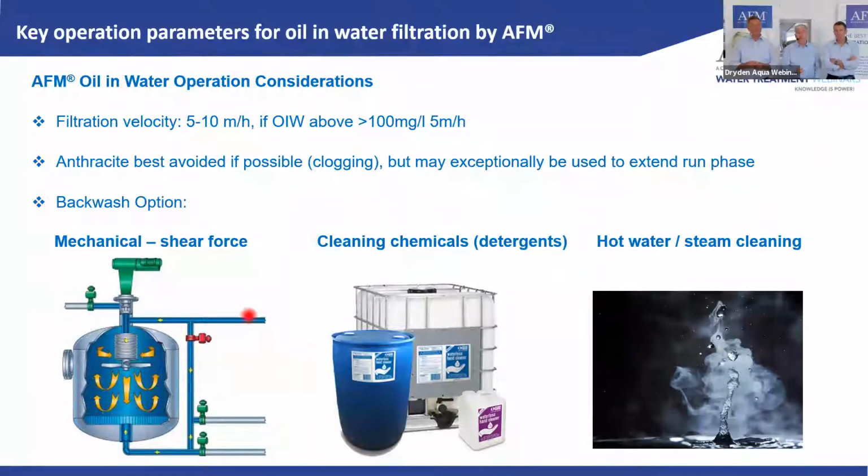So backwash options with the oil treatment, you typically have 3 options. Mechanical cleaning, which you do in produced water. You have very specific filters, which is very intensive with shear forces, and where some filters are removed, as we have seen, to help avoid the loss of media. Sonic would be a perfect example. Then we have cleaning chemicals, as we have just seen with Kaigon. You can use detergent cleaning, and that's done in the oil industry, or in applications where oil is removed. Or of course, also in oil industry applications, hot water steam cleaning. That's also very often done.